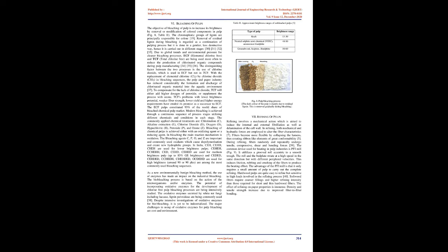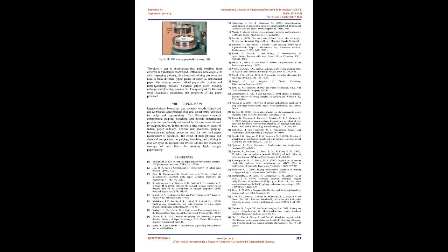C. Chemical thermomechanical pulping, CTMP. Chemical pretreatment was introduced to overcome some of the above problems associated with mechanical pulping. The process starts with the penetration of 2 to 5% sodium sulfite and chelating agents at a pH of 9 to 10. The mixture is heated for 5 to 10 minutes at a temperature of 120-130 °C and is subsequently refined. The yield is in the range of 86 to 90%.